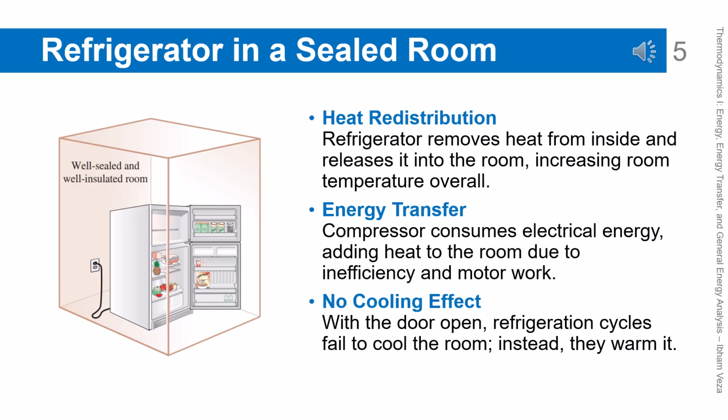Refrigerator in a sealed room. Much like a refrigerator, it removes heat from its interior and releases it to the room, while the electrical energy consumed by the compressor is also converted into heat. In a sealed room, no energy actually leaves the room system. As a result, the total energy inside the room increases. The average room temperature will rise, not decrease. This example emphasizes the importance of considering the overall energy balance.